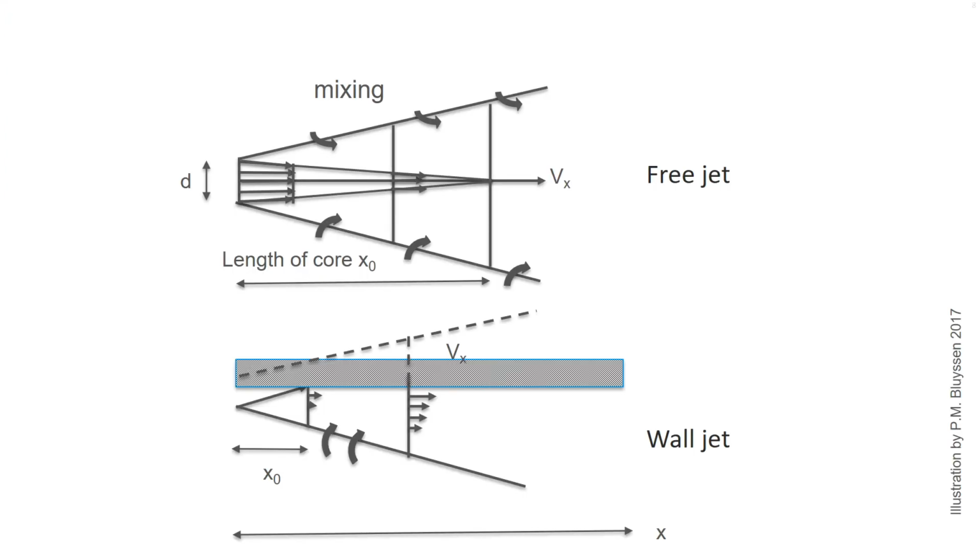The hole through which the air supply takes place is usually covered with a diffuser or grill. The direction and the throw of the air jet can be controlled by the position of the blades of the grill. And when the supply is just under the ceiling, the air will follow the ceiling, it sticks to the ceiling, resulting in the so-called Coanda effect. Mixing of the airflow occurs in this case only on one side.